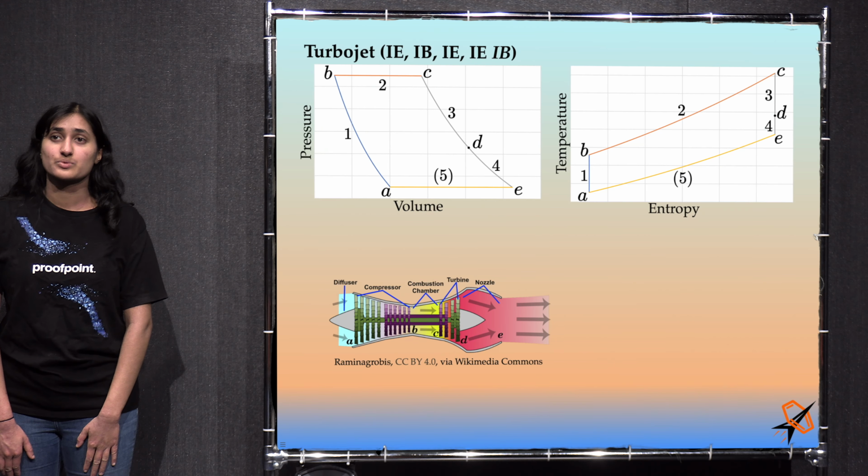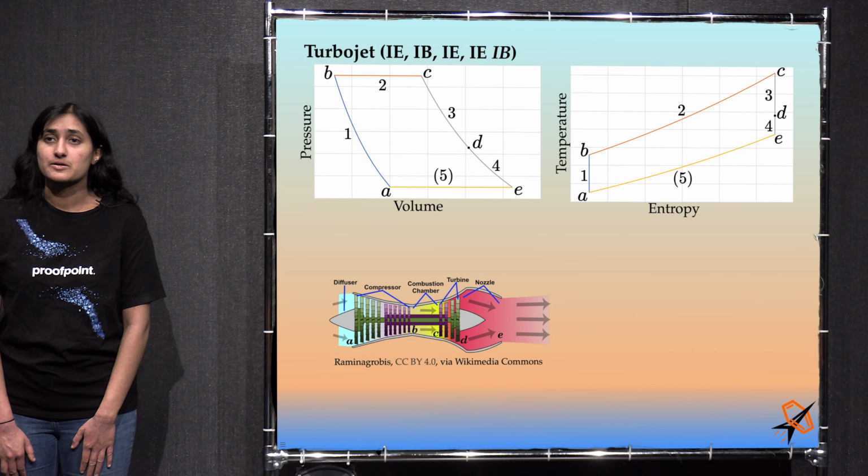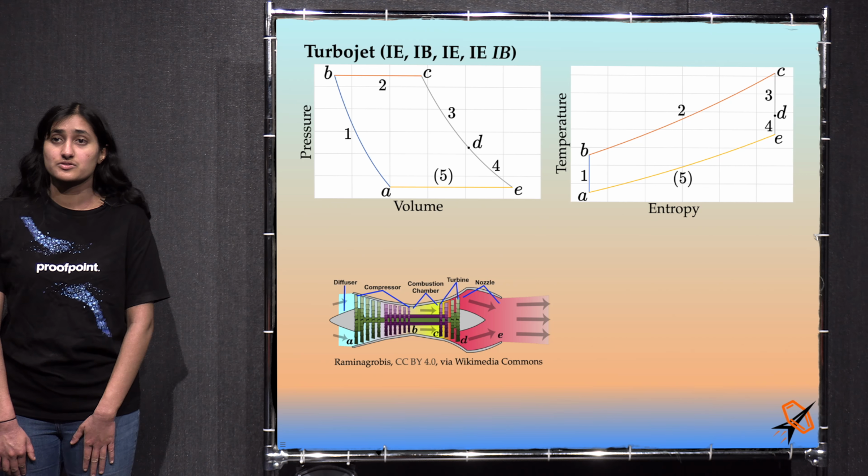The turbojet cycle is what is used to model the turbojet engine. The turbojet cycle is basically a modified Brayton cycle. The turbine creates just enough power to drive the compressor, and the still at high pressure exhaust is expanded through an isentropic nozzle to create high velocity exhaust that propels the jet forward.